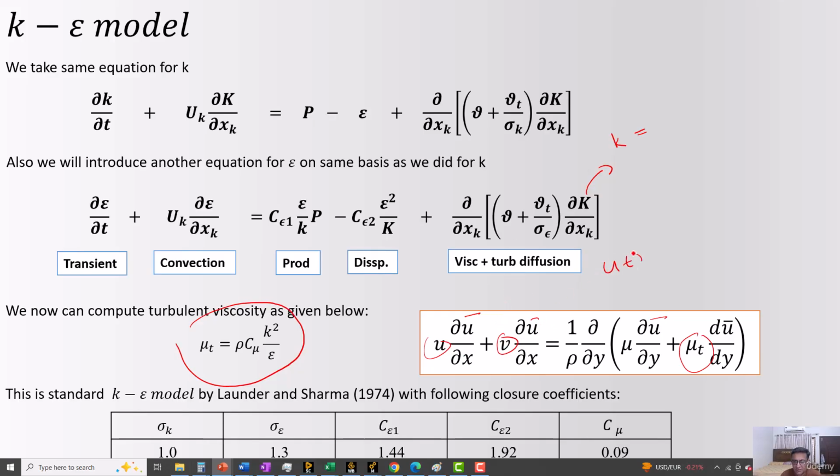u instantaneous velocity. But I told you, this term that we are putting here assumes that the fluctuating component, the disturbance, is a constant value on both the negative side and the positive side, and that does not change with turbulence. So that's a big assumption, but this is how the eddy viscosity model works.